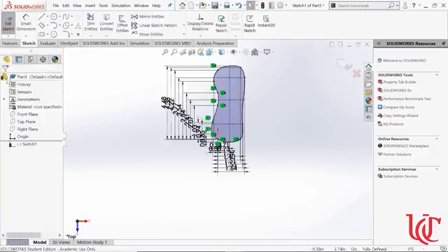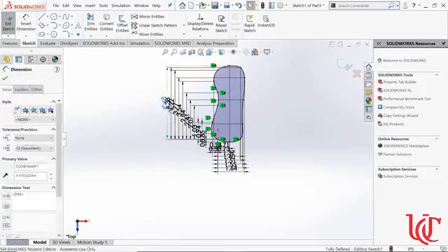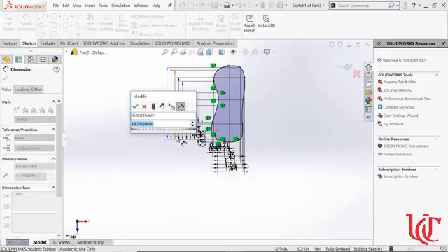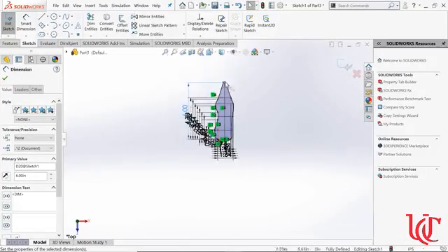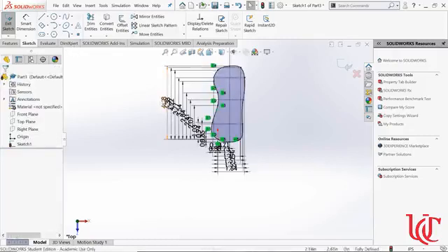But for me, if I say fully defined sketch and click on that green check mark, it actually does define it by giving it a whole bunch of dimensions to where all those points on my spline were. If I change one of the dimensions for that point, so like this was my vertical distance from my origin up to this top point, let's say that wasn't the distance I want, and I wanted it to be 6, for example. Then it moves that point while keeping all the rest of them. So it'll look kind of funky if you don't first define those points to be where you want them. I'm going to undo that.